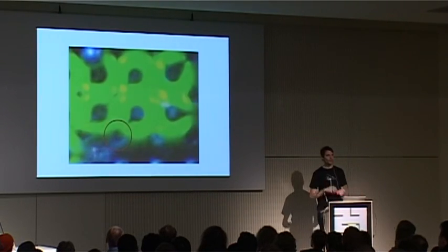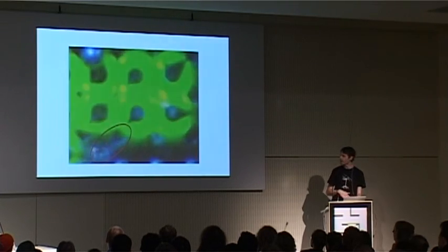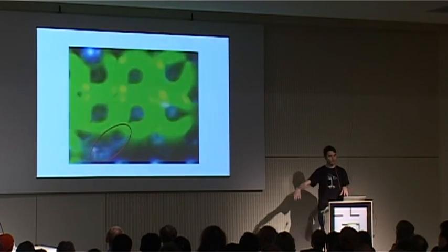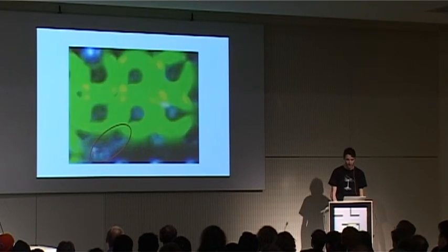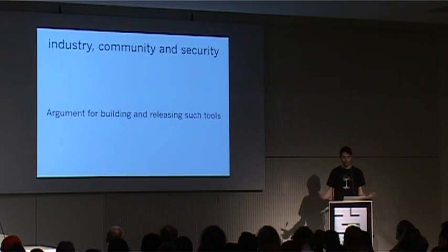It's either the bottom left or the bottom right. In this case, I guessed the bottom left, which you can see here, and I exposed this, and I was actually able to successfully map it to the rest of the board and then go to another device and actually use that JTAG interface. So you might find all sorts of crazy solutions that are in themselves a 'what the fuck' moment, where you don't believe this works.